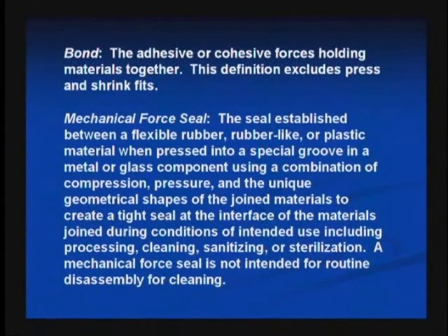definition, primarily to get this point across, that a mechanically forced seal is not intended for routine disassembly and cleaning. It wasn't like a normal O-ring. Once you started digging around in there with your little screwdriver, it was shot. You had to have a special way of getting a new seal put back in there. You can't put it in by hand. It's not a finger-tight seal. It takes a lot more compression and pressure to get it inside. So it became